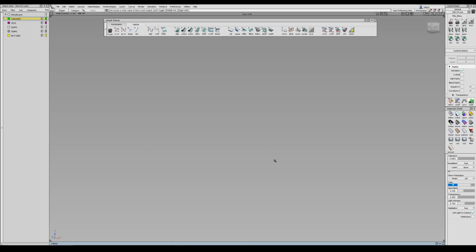perspective window. I pretty much work exclusively in perspective and use the view cube to navigate to all of the different regions or views, and I have orthographic faces turned on. Just click on this little arrow down, perspective with ortho face. The object lister I am a huge fan of.